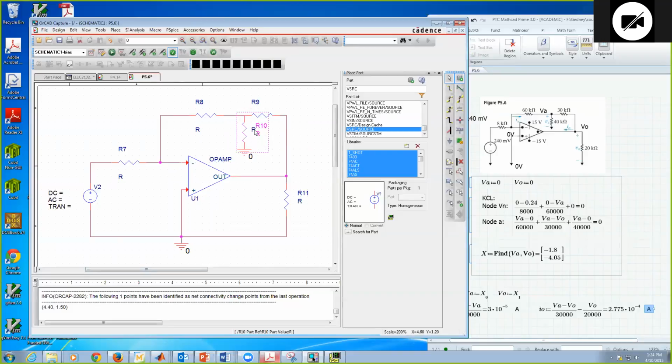The next thing is, I see these two resistors, and there's a little bit of confusion as to which R belongs to which. When I click on this, I see the R10 highlight, so those belong to this resistor. I click on this, and this R and that R9 belong to this resistor. So to avoid some confusion, I'm going to move these over here, and I'm going to move this up here and see if I did that right.